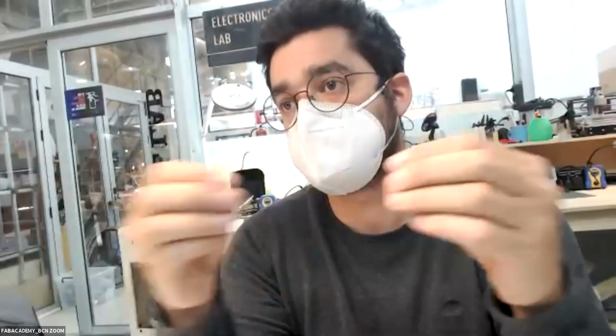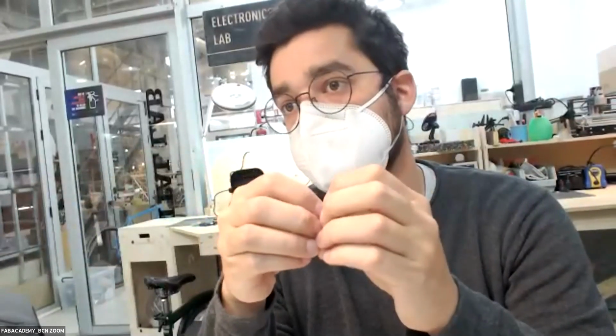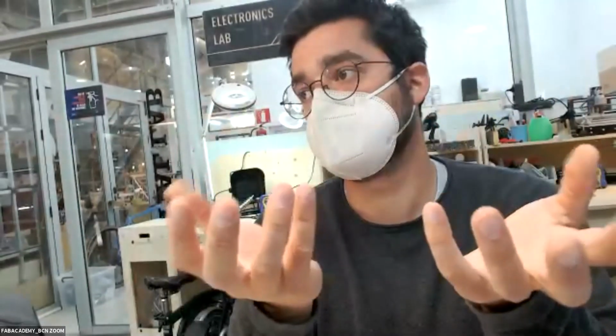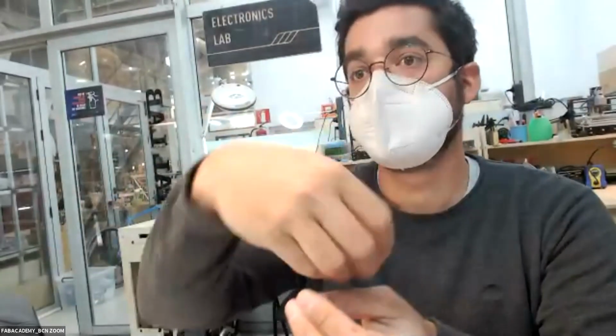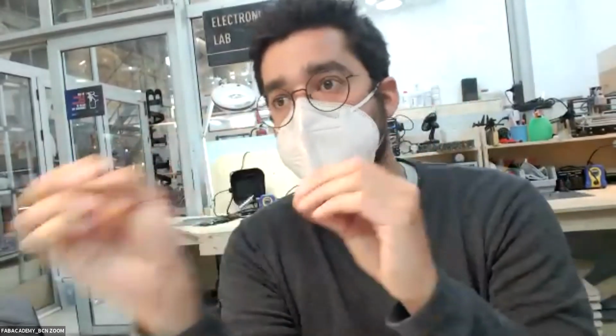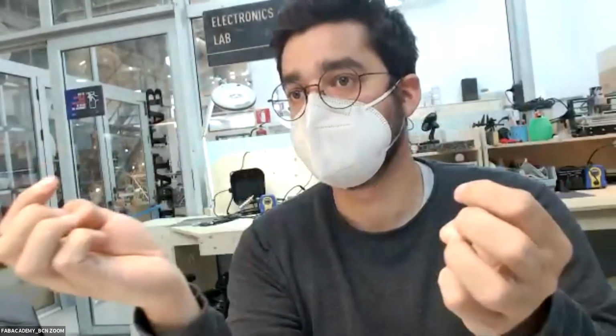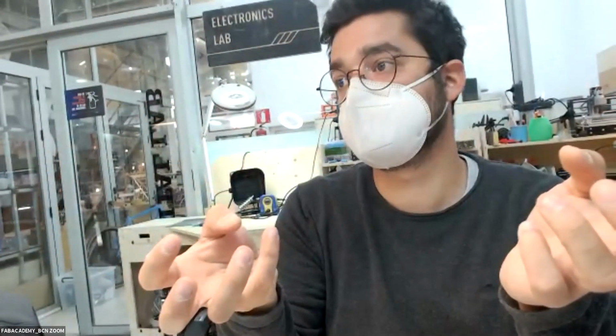So yes or yes, we need to know how to make the simple scripts for Grasshopper and be able to make the file for the robotic arm. You saw that actually within the robotic arm, it's really similar to a 3D printer. We make a file, we put in the USB. The only thing we need to do is a previous setup that is actually the calibration of the tool. That is really important. And to acquire this data and put it in the Grasshopper. What is the most difficult part? That the robot does exactly what you want to do without getting into a singularity. That is the point that it cannot turn in that direction, and you need to change the object rotation, etc. a little bit.